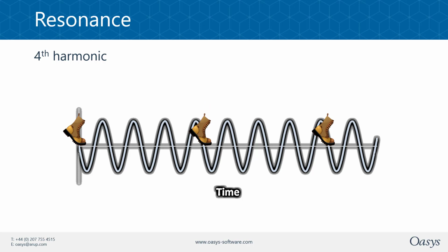Now, I've heard a fallacy that says you need multiple regular bays to build up resonance. This is not the case, because vibrations over multiple bays tend to have a large modal mass, which lowers the response. In fact, isolated bays that do not interact with the rest of the structure can have a high response, as I mentioned, because of low modal mass. Now, what is important here is the physical width of the mode, and thus how many footsteps can fall in that location. How many footsteps do you get as somebody walks across their area?